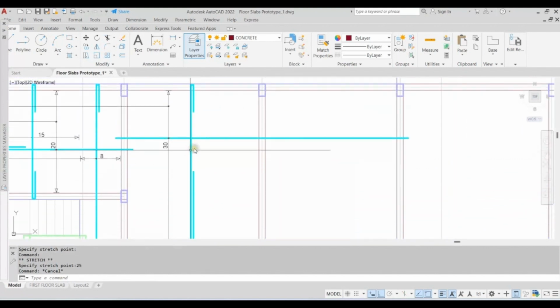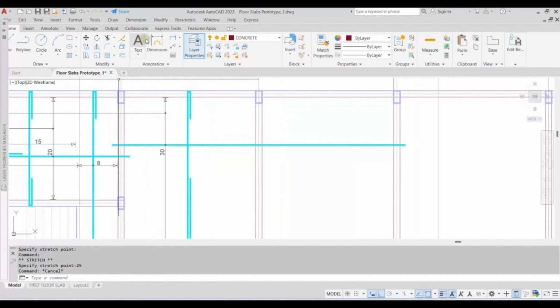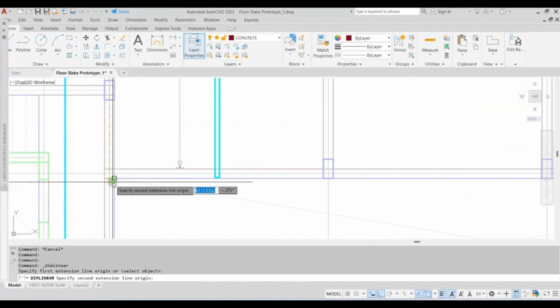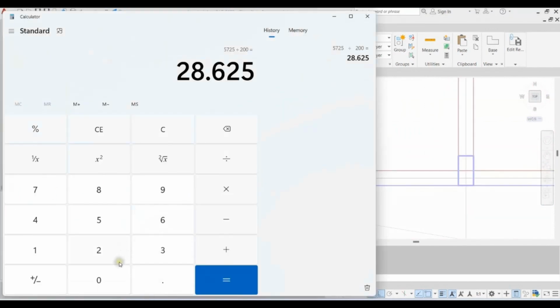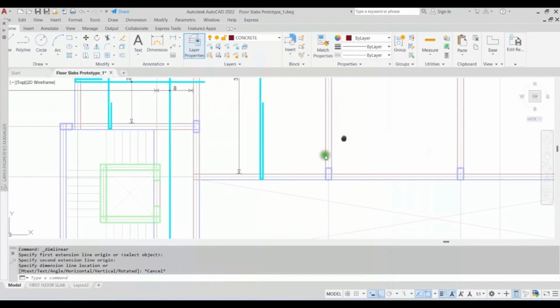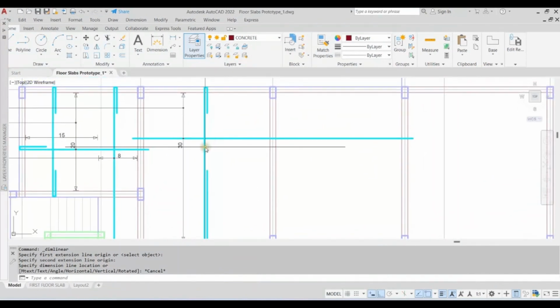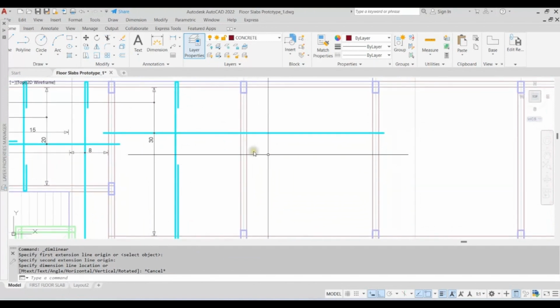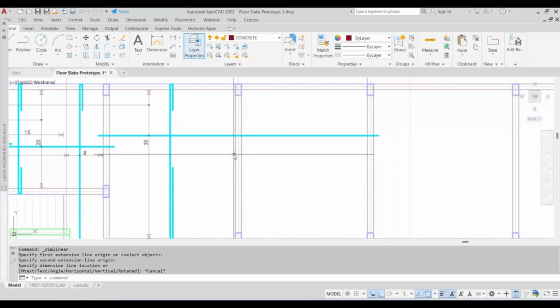Then this is it. So the next thing we are going to check is our 0.15 of the length. 0.15 times the length. So if we do 6,000, this is 900. Just to avoid confusion, just to make my drawings consistent, and for whoever is placing this reinforcement on site, it will be easier, there won't be confusion.